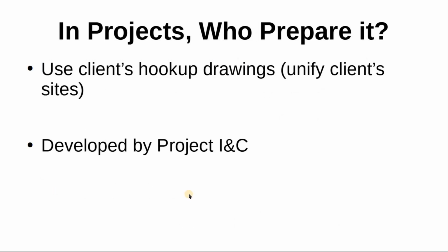So in a project, who prepares it? The first question is, does our client have a hookup drawing? If the client has a hookup drawing, then let's use it. We may modify it if needed, but if not, just use it. This will unify all the client's sites, so everything will look and feel the same. If there is no hookup drawing for that specific instrument, then the project INC will develop this hookup drawing.